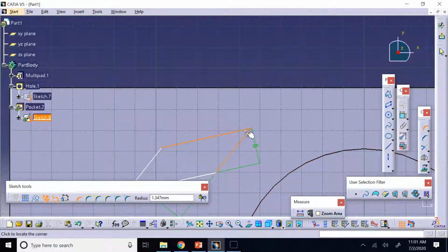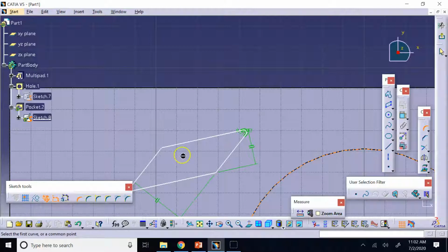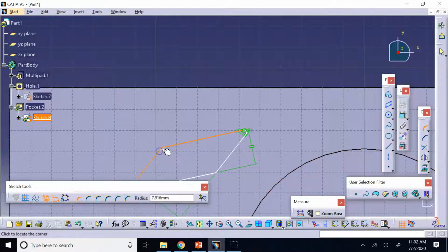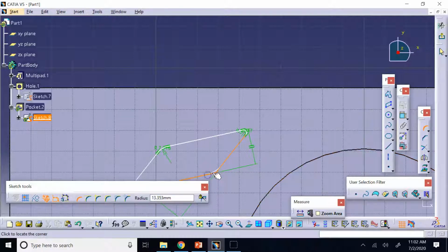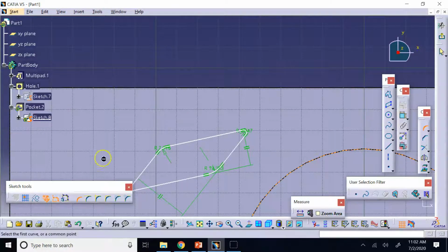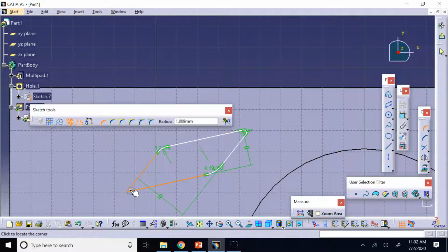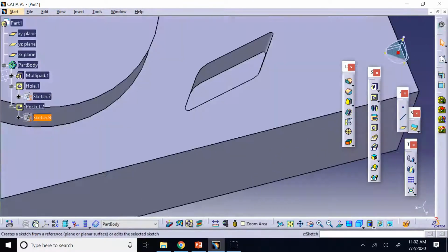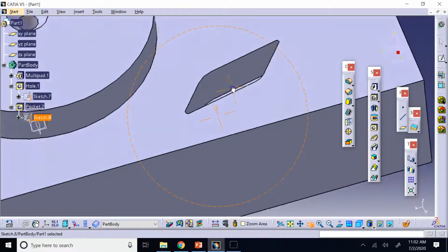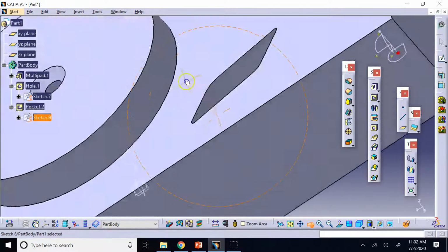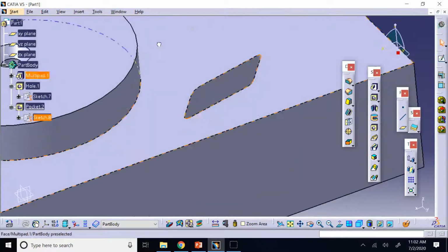So you have to do a little bit of fillet, something like this. How much is that? Depends on the size of the tool that you're using. But it is really impossible to create such sharp corner in real life. So you might be able to get something like this, okay? But if you want it perfect sharp, it's not doable with a milling machine. So just wanted to remind you about that very important point.